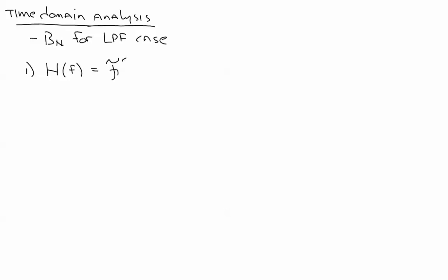Time domain analysis. This is for noise equivalent bandwidth, and I'm going to do it for the low pass filter case. First of all, I'm going to recognize that my transfer function is the Fourier transform of my impulse response.